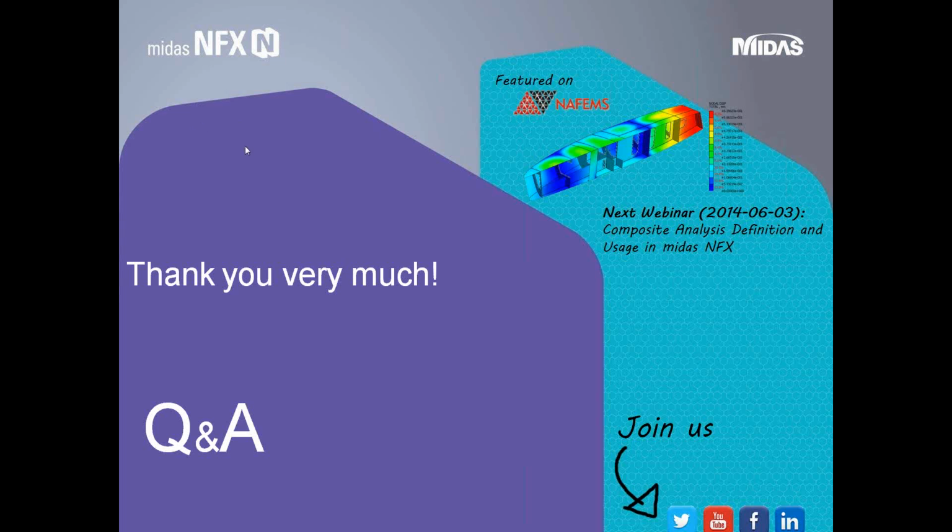Okay, there are some questions. Do we have a way to know the flow regime after the deformation? Yes, you have a way to do that in NFX, and we will send you the information by email on how to do that. Do you have an integrated fan library? We don't have a library, but we have the possibility to import the curve. So if you have the fan curve, you can import it directly.